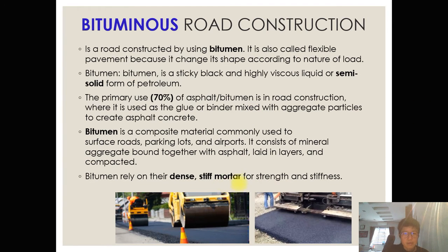And bitumen is used in all situations when you have a bituminous surface, obviously, and it relies very much on its dense, stiff mortar for strength and stiffness. So as I said, if you see in road construction or road rehabilitation, when trying to repair a pothole or things like that, you see that they have a little trolley and a tank that contains, if you like, melted bitumen. Okay, in room temperature it is actually semi-solid. You can still poke your finger in it, but when it's hot, obviously it's pourable.